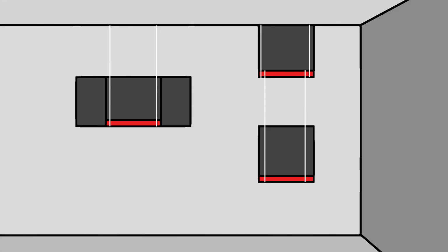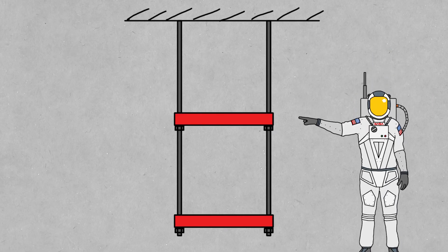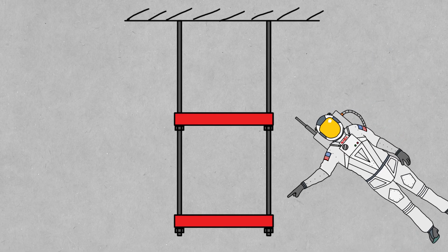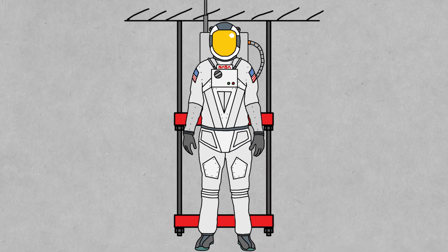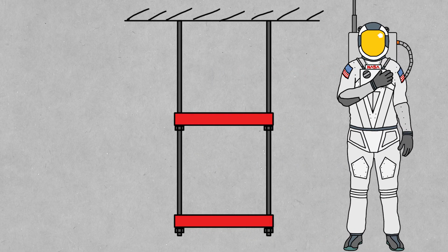There were 3 walkways in the hotel that connected the 2nd, 3rd, and 4th floors in different parts of the hotel. The 2nd and 4th floor walkways were stacked on top of each other while the 3rd was set off to the side. The design originally called for rods to pass through the 4th floor bridge to connect to the 2nd story bridge. This would mean that each rod would hold weight from both of the bridges. The problem with this design was that it required nuts to be threaded all the way up a rod to where the higher bridge would be held.